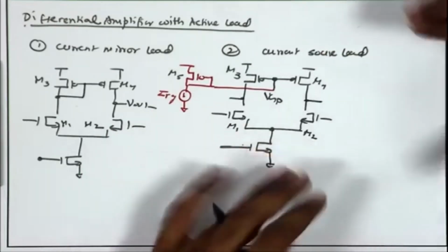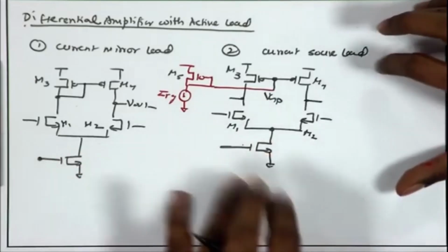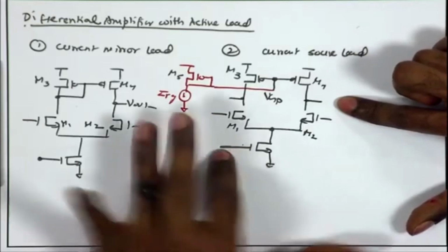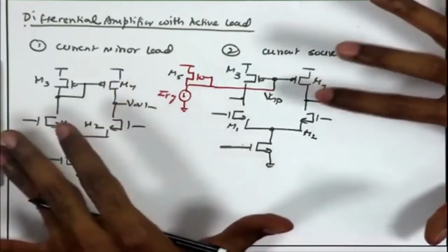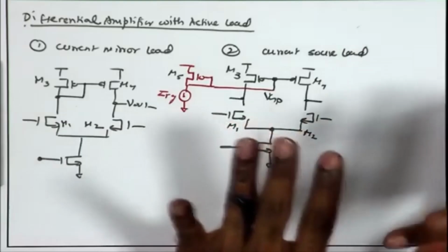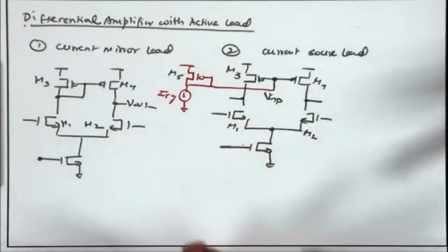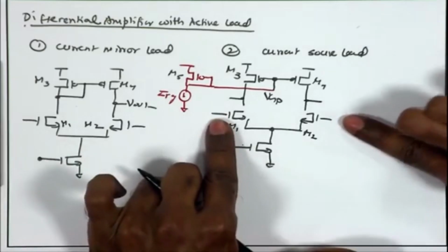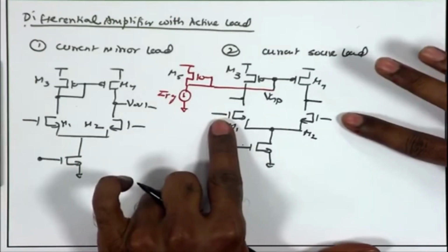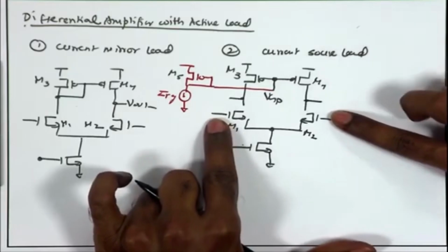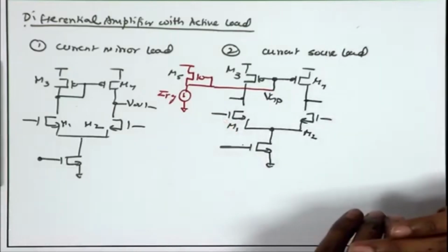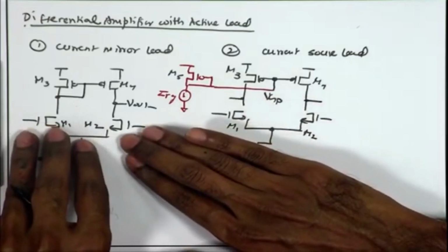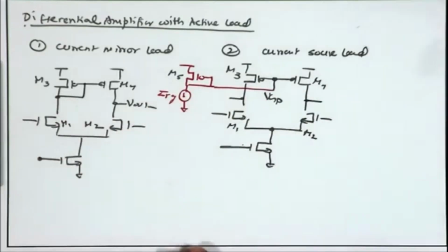Even for digitization, people now prefer fully differential amplifiers and comparators, which can have better robustness. So, in today's mixed signal design, we can have the entire chain up to the ADC, amplifier and comparators, being completely differential. So, we are going to use this fully differential amplifier as the main amplifier in our design. This is going to be the first stage of our front end amplifier, but we are going to need assistance from another current mirror load amplifier with a single ended output. We will see why.